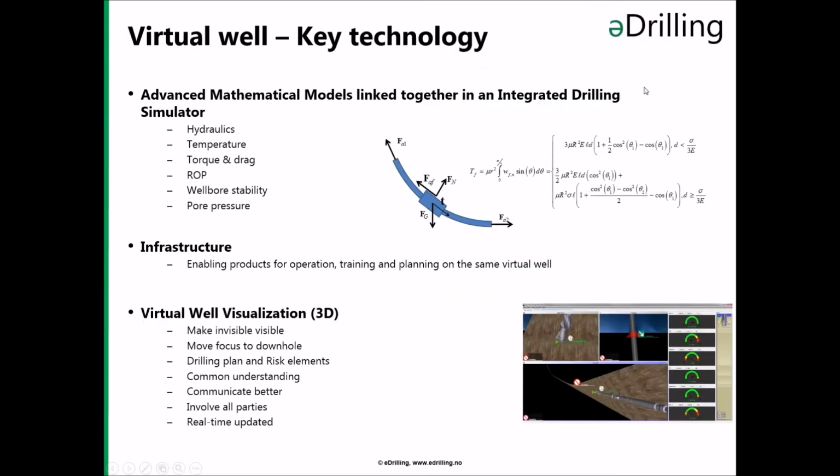One of the key technologies is what we call the virtual well, and the virtual well is a collection of advanced mathematical models linked together in an integrated drilling simulator. These models are the hydraulics model, temperature model, torque and drag model, rate of penetration model, wellbore stability model, and pore pressure model. We also have an infrastructure which links these models to the environment, enabling these models to be used for training, for real-time operation, and also for planning on the same virtual well.